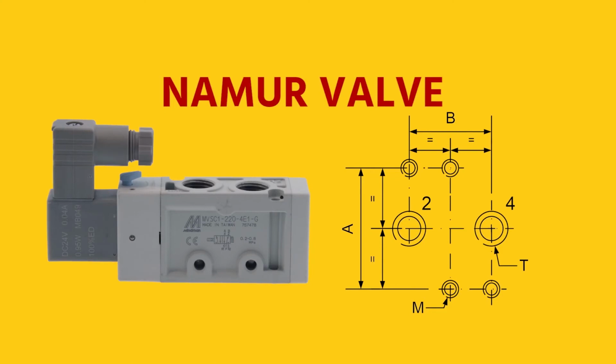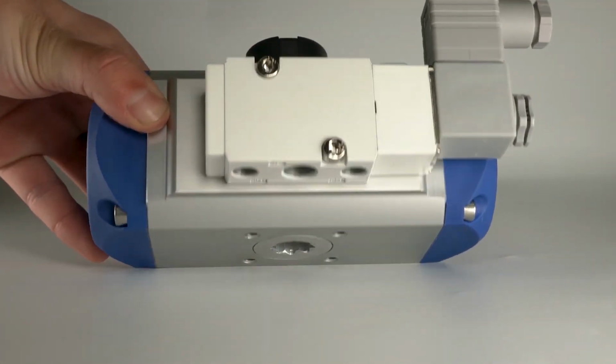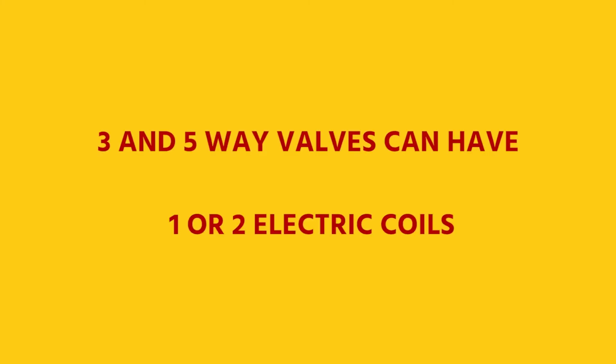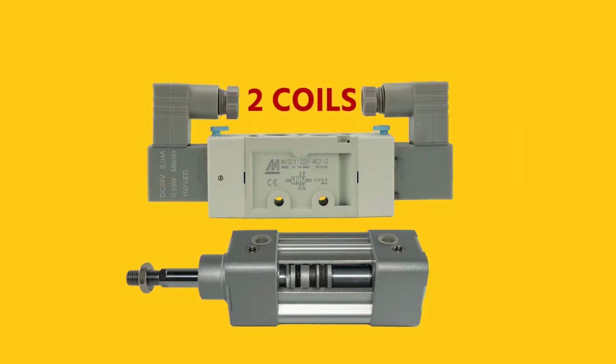Namur valves are a special type that have a standardized design to directly mount them to a valve actuator. They are easy to mount, compact, and reduce the number of hoses and fittings. 3- and 5-way valves can have 1 or 2 electric coils. One coil means that the valve returns to a rest position with a power loss. 2 coils means that it switches by providing a short pulse to one of the coils. With power loss, these valves remain in the latest position.